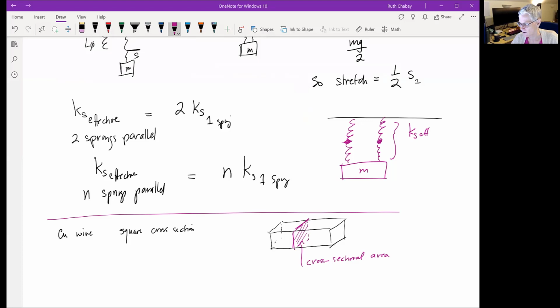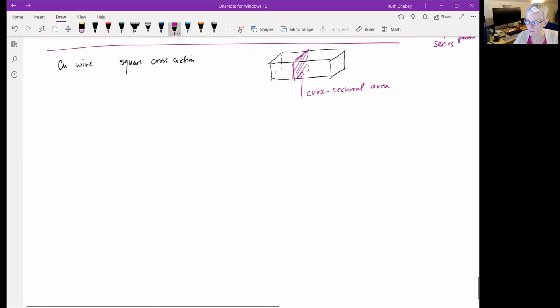These are all identical springs. So each of these chains would be half as stiff, but we'd have two of them, which would make it twice as stiff. So it is the original K sub S times a half for the series times 2 for the parallel, which does indeed give you the same effective spring stiffness. So that's the game we're going to be playing here and talking about chains of atoms.